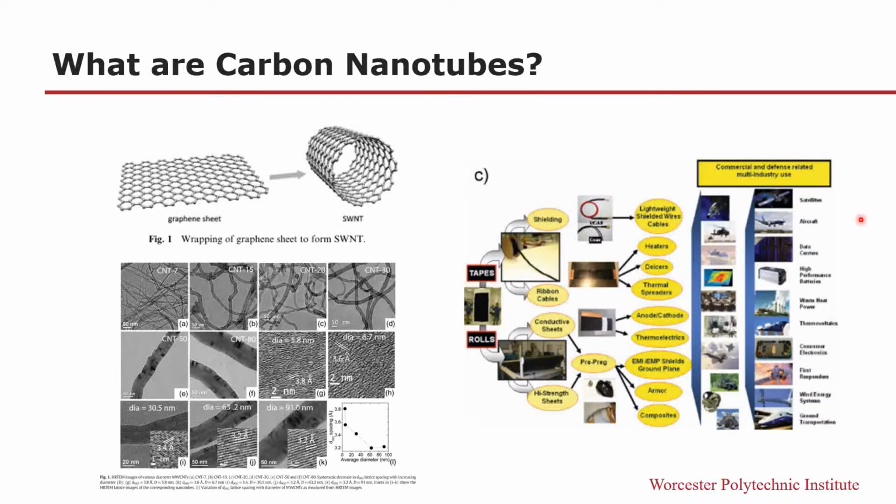High-quality carbon nanotubes are often produced by chemical vapor deposition under full or partial vacuum. Pyrolysis of various hydrocarbons have also been shown to produce large quantities of carbon nanotubes, although often in a wide range of quality. Their applications range from structural, such as composite materials, energy applications, such as battery cathodes or hydrogen storage, medical applications such as drug delivery systems, and electronic applications such as sensors and capacitors.